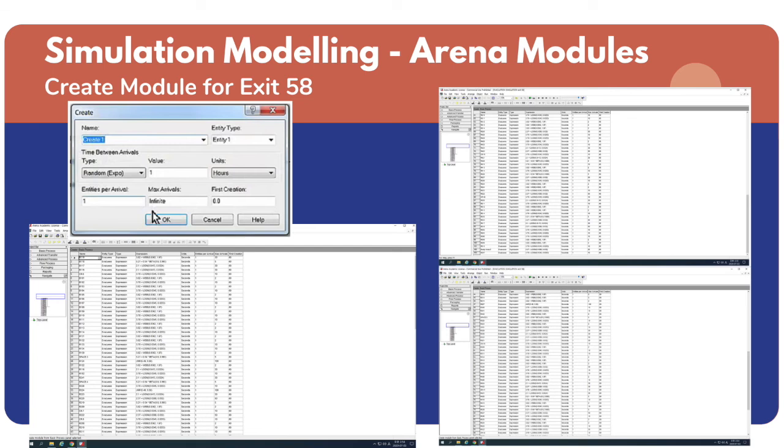The Create module refers to the arrival of the parts to the system. We use the Create module as the rooms of the building, where the time intervals were established along with the total number of occupants per room. For the time between arrivals, we chose the expression option to declare the distribution obtained from the Input Analyzer fitted for the room being analyzed. For example, Create Module 1 was named Room B119, and based on its max arrivals, it has 30 evacuees in total. Therefore, it is a lecture room.